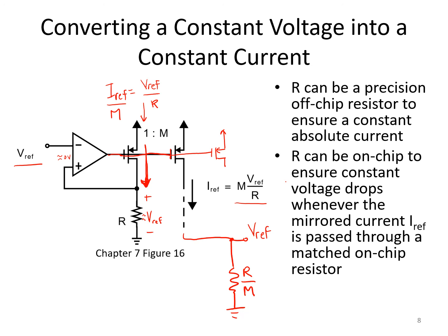They will vary with the temperature coefficient of polysilicon resistors on the chip, but as long as the resistors are relatively well matched, we can recreate the bandgap reference voltage Vref wherever we need to, anywhere across the chip. And we cancel the polysilicon resistor temperature dependence because we multiply Iref times R over M, so the M over R gets canceled here.